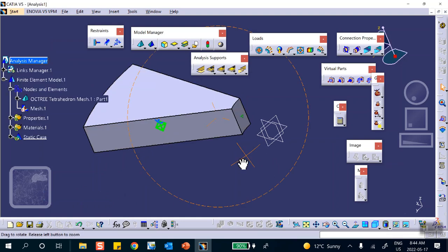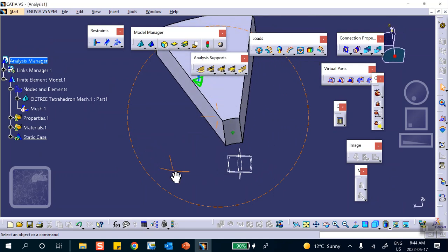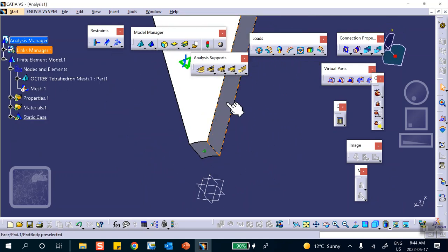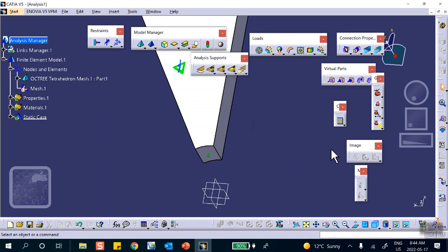And let me change the rendering here also. Good. So, do you agree that this is a plane of symmetry? We said that these sectors are the same. That's why we took a 30-degree sector, for example. That means that when this disk is rotating, with respect to the disk, things on these 2 planes just radially move out. That's it. They don't go to the side. They don't go left. They don't go right. They just move out. That means that plane remains a plane. That's what a roller is. Okay, a plane of symmetry.